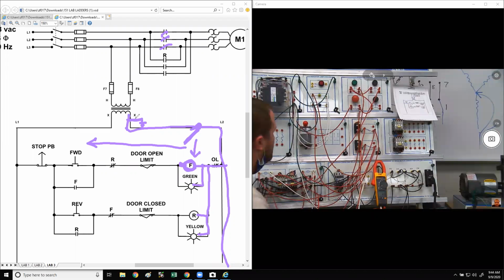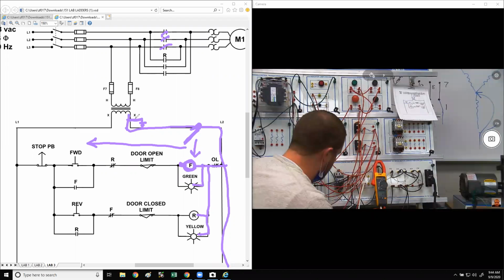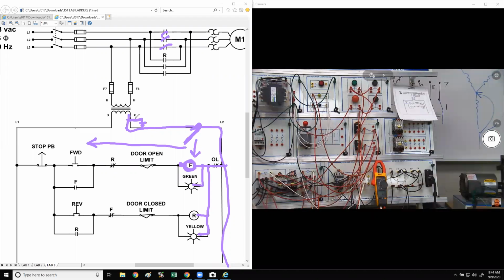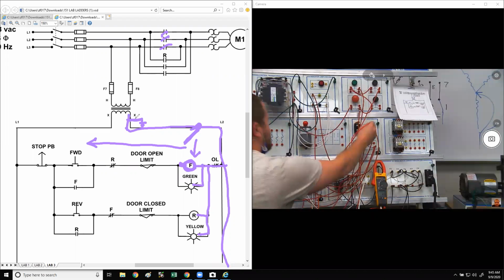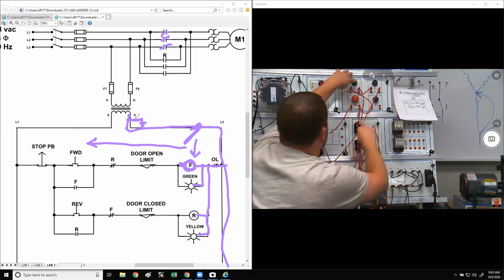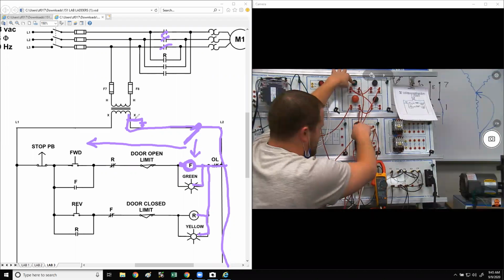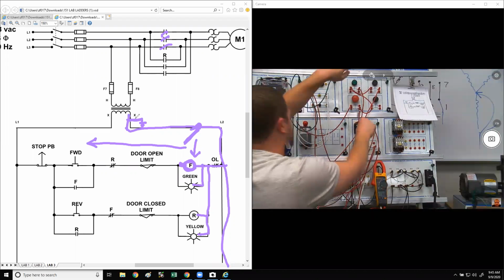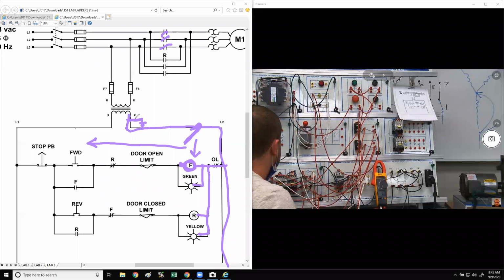Okay. So I've got nothing, nothing, and where's the next place I'm looking? The line side of the limit switch, which is, I've got it on the common right here, but anything? Nope. What's the next place I'm looking? Load side, that reverse contact, normally closed. What's that called?